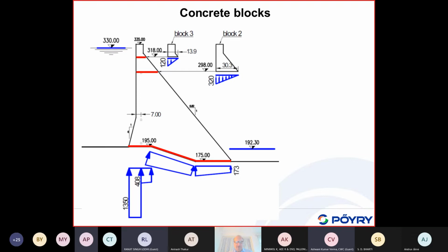2 meters, if I may say, if you look in a stability, the thickness of the dam here is about 14 meters. So 2 meters movement out of 14 meters is basically, if you look into the sliding stability of this part, if we have a reduced contact area, it is still sufficient.